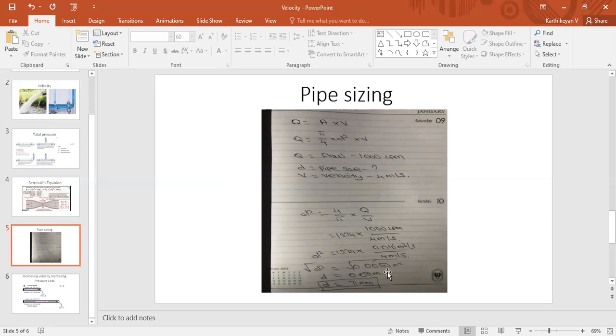After running the calculation, I noted that the velocity at a particular point was more than 500 meter per second, and the source pressure requirement was more than 30 bar. You can imagine, the maximum listed fire pump pressure available in the world is 294 psi. So a pressure of more than 30 bar is not practical.